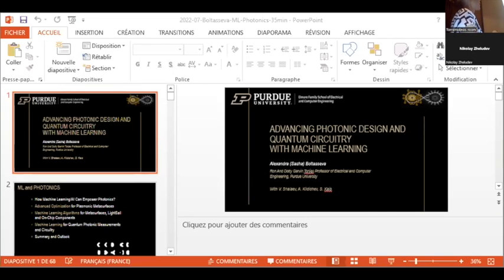So you can have an hBN layer with an emitter on top of a silicon nitride waveguide structure or the coupling area, or you can have it sandwiched, and depending on the architecture, you can have different designs that would perform better or worse. What's also very important in this specific case for optimization is that you can design, using topology optimization, the structure in such a way that it will be robust, for example, to the position of your emitter.